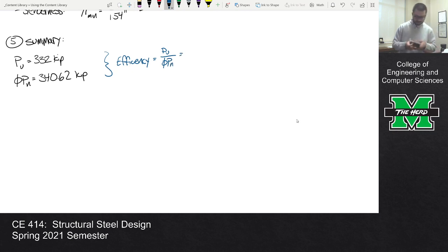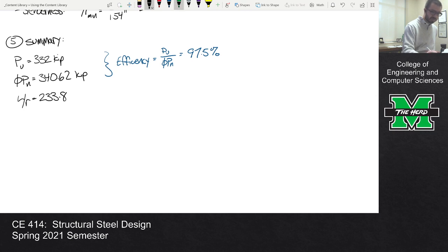And anybody have a number on that? 97.5%. So that's not bad. That's a pretty good number there. All right. So the efficiency is 97.5, and we know our L over R was 233.8. So use a W12 by 35.